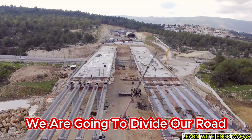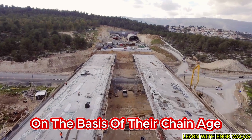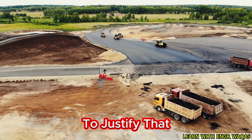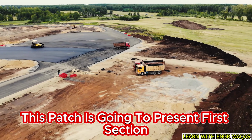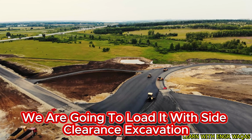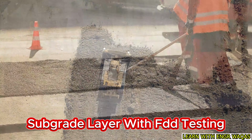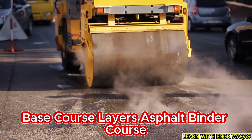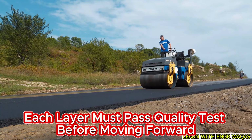We are going to divide our road construction project into different sections on the basis of their chainage, like 0+000 to 2+000, to show that this batch represents the first section, then the second section. Then further on we are going to load it with site clearance, excavation, subgrade layer with FDD testing, sub base layer with CBR testing, base course layers, asphalt binder course, asphalt wearing course. Each layer must pass a quality test before moving forward.